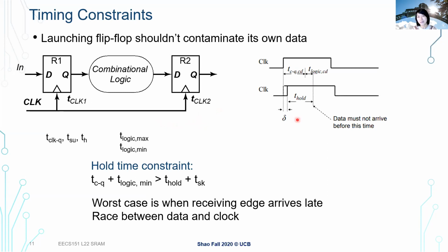So you really need to think about the worst case scenario. When you think about the different components of your circuit, you really need to compensate not only for the normal, ideal case, but also for the non-ideal case, where clock skew plays a fairly important role in design, especially when you get to really large scale.